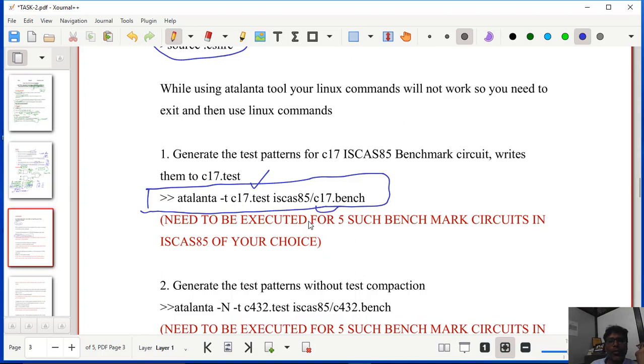Now this is going to be my input and c17.test is going to be my output. The command is Atalanta -t, space, and this name you can give according to your own wish, c17.test. This .test is important, which means for the file c17.bench, it is going to generate a test vector. The test vector will be available in c17.test. Where is that c17.bench file located? It is located in ISCAS 85. So we have simply given this.